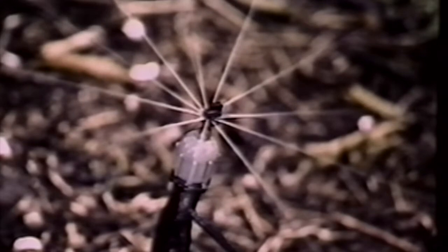The bubbler type system applies water to the soil surface as a small stream or fountain. Discharge rates are greater than for the drip or subsurface systems, but generally less than 1 gallon per minute. Spray systems apply water by a small spray or mist to the soil surface. Consequently, the air distributes the water rather than the soil, as is the case with the other three systems. Discharge rates for spray-type emitters are generally less than a half gallon per minute.